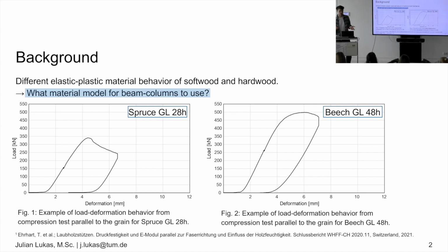So why is this important for stability behavior? It's important because we have a reduction of our E modulus. When we look at that, we get our E modulus from this line here, and when we get to the top it gets lower and lower until we have no E modulus, or we lost every stiffness we have in our material. That's why I wanted to look deeper into stability: how does it affect the load bearing capacity, and how is it even modeled?